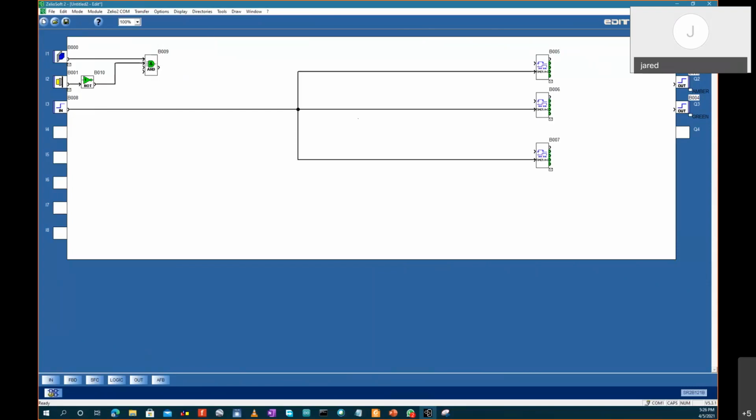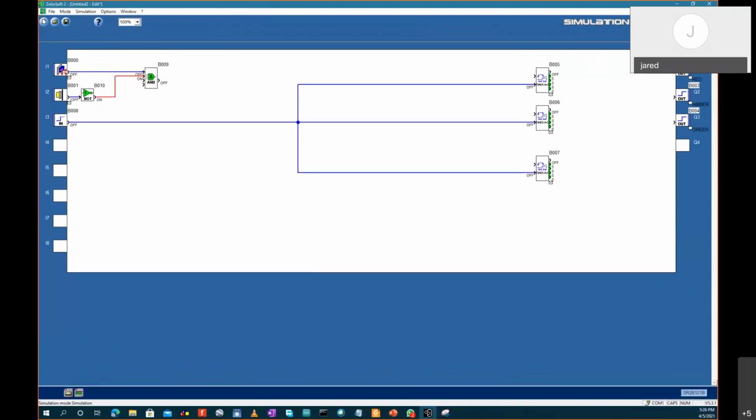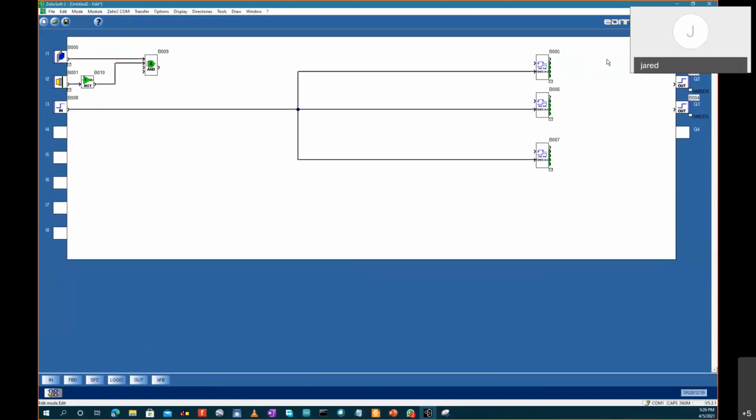So this is like your timing, and then we're doing small progress. So see, it's already on, the timer is already on. So if I press this one and I run, the timer will be active. Okay, it changes state from off to on. So if I press this one, off. Yeah, but initially it's off. Yeah, that's how you do some small programming. So in PLC, it's advisable you do incremental stages of PLC programming. If you do vast changes, you can do versions. The same way you do Git versions, do it the same way in the PLC.